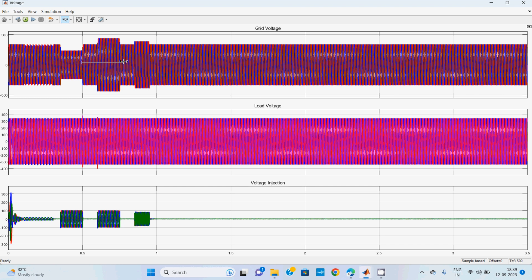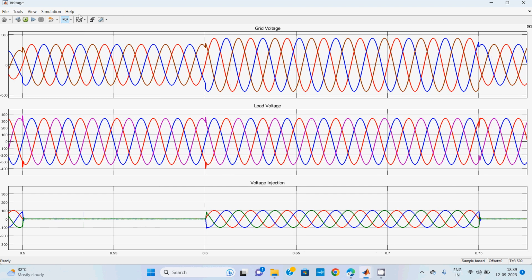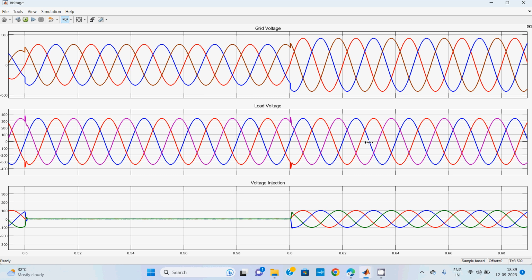And this is voltage sag, voltage swell, and voltage harmonics. Whatever disorder signals the grid generates are reduced or compensated by the series compensator. Then the load can get an accurate, constant voltage magnitude by injecting voltage here. This is the voltage injection. Suppose voltage sag or voltage swell occurs here; that is quite opposite to the proposed one. That is the advantage of the design.